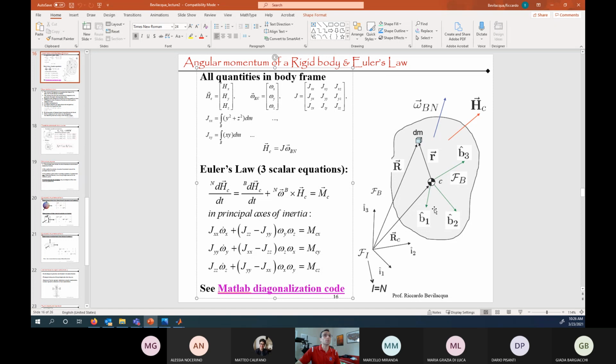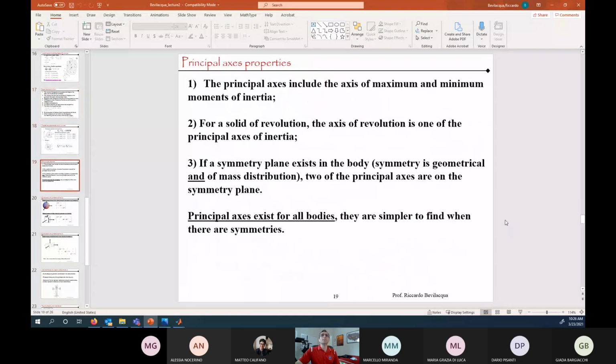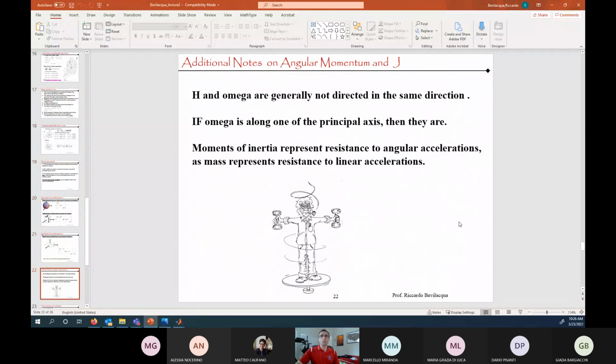There are 2 different vectors. You obtain H by pre-multiplying omega by a matrix, so H will in general be different from omega. And these are obvious things, but I see this error made over and over again by students, and not only students, professors as well. We tend to jump to conclusions and simplify things, but special cases can be represented by expressions that collapse into parallel vectors, but in general that's not true.